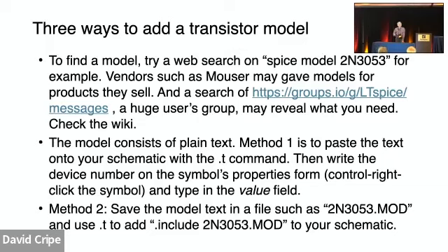It's the name that appears in that text, which might vary a little bit from the common name, so you kind of got to look at that. The other thing is to save that text in a file and use a .include statement to tell it to look for that file. You programmers use the include statement for libraries and stuff. It works that way.